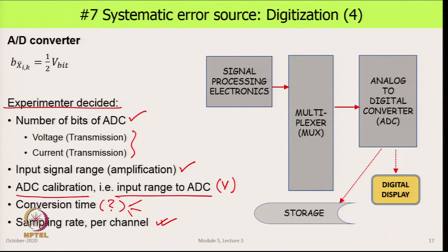If we were looking at a multiplexer, what it will do is the A to D converter will take this signal, digitize it and put it out. Then it will give a signal back to the multiplexer to say that I am ready to take channel number 2, send it. So, it will then disconnect this, connect this and convert it into a digital signal. Then it will send a signal and say I am ready for channel number 3, this gets disconnected, number 3 gets connected and now this gets digitized. So, like this it goes through all the channels on this and then the cycle is repeated.